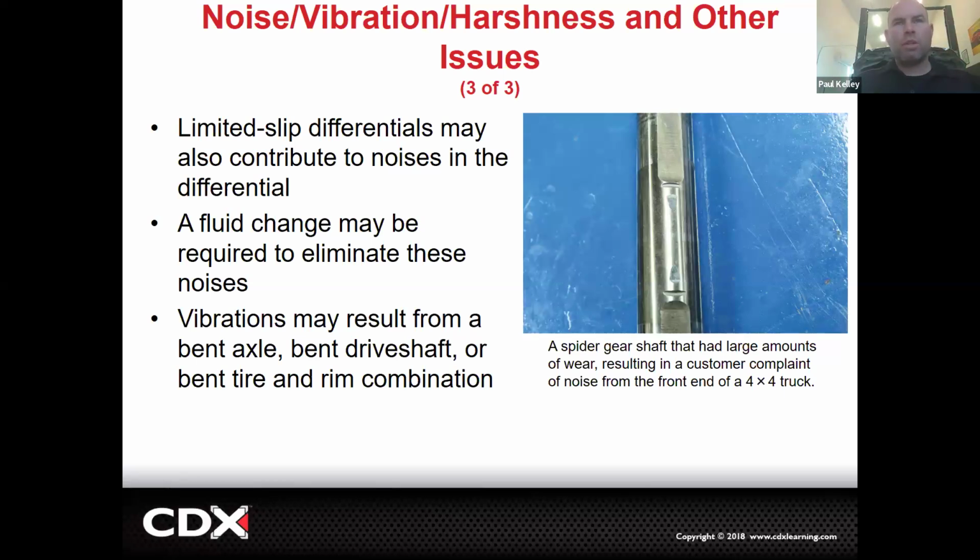And it also had a locking differential, but the way that the G80 Eaton locking differential worked was it didn't slowly apply the clutches. You had to slip the wheel enough and then bam, it would be engaged. And you could feel it. It would only do that when, after a snowstorm, you'd have spots of snow and dry pavement and snow and dry pavement. So if you were just cruising and you were on the dry pavement, everything was good. But then when you hit the snow, the rear wheels might start to turn. And if one rear wheel turned faster and the other wheel turned slower, it would engage that G80 and it would bang and shudder and there was noise, there was vibration, there was harshness, and it was all normal. It was entirely normal because the differential was locking up when you went across those snow drifts. So the locking diff stuff adds another layer, if you will.